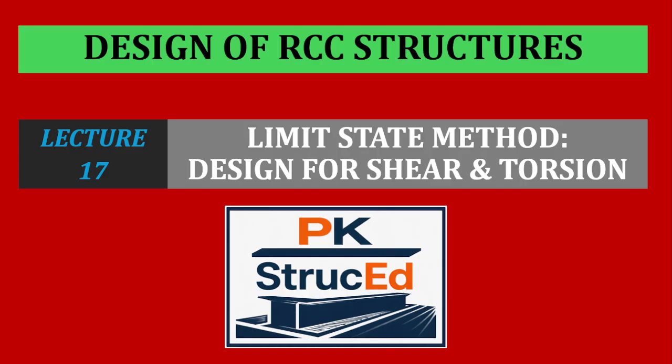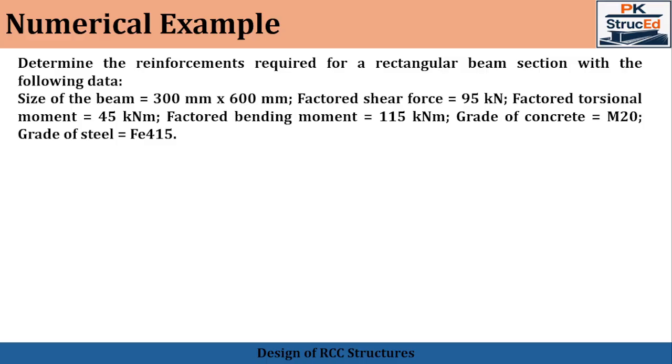In real life examples, shear and torsion become critical in edge beams, in slab beam systems, beams that are supporting cantilever balconies, beams carrying eccentric loads, even staircase beams and frame corners in buildings. A beam that is safe in bending may still fail in shear or torsion if not properly designed. With this introduction, let us proceed to the design of RCC beams subjected to combined bending, shear and torsion using the limit state method.